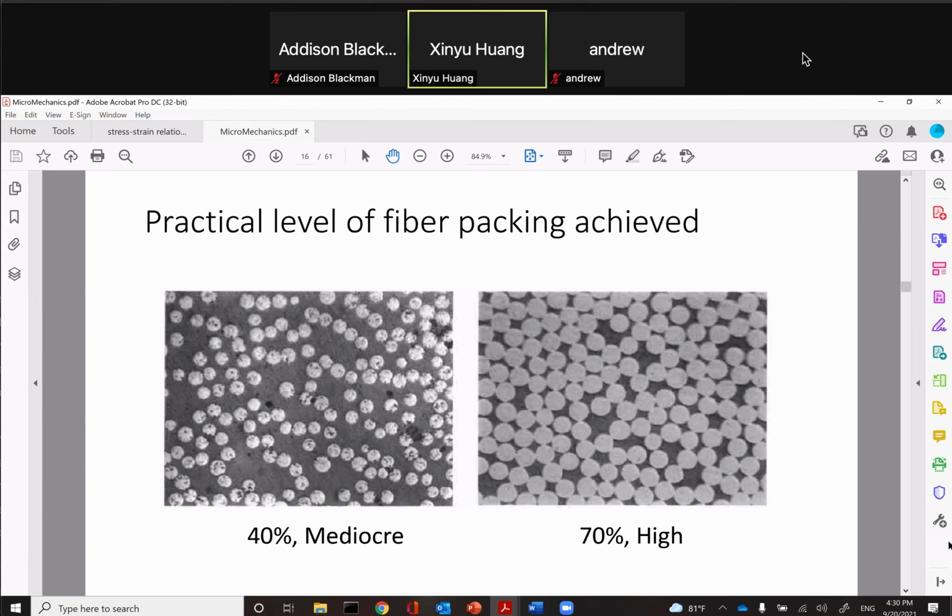Now, what the Reuss model tells you, if this is a glass fiber polymer matrix composite, your glass material is 85 gigapascal modulus. Your matrix 3.4 gigapascal. If you cut a piece of material, you measure your modulus in this transverse direction, you got 11. It's much different than polymer, but you're not achieving the glass level. The glass is 85, right?